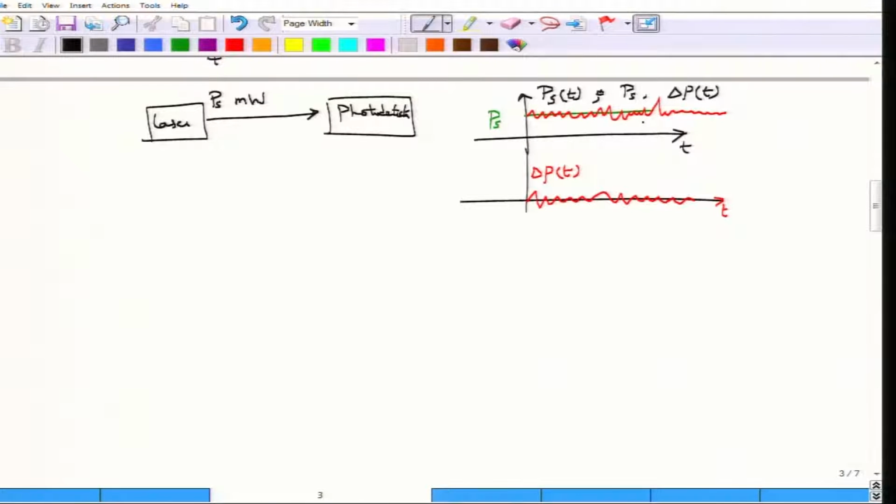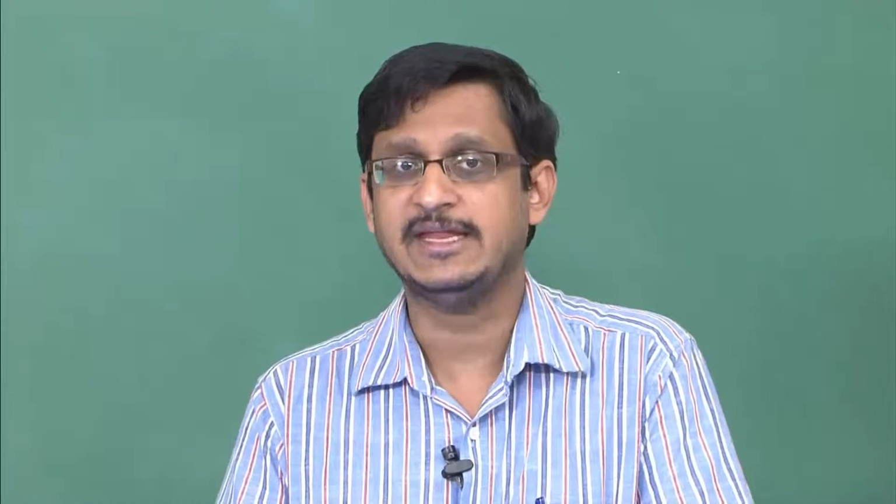If the power is not fluctuating, if the frequency is not changing, if the phase remains constant, then I cannot communicate anything. So, everything is constant, I am not communicating any data to the receiver. If I want to communicate, I have to change these characteristics. So, I have to change the power or equivalently intensity, or I have to change the phase and frequency. So, we will see how this can be done by postulating certain optical transmitters, or optical modulators.